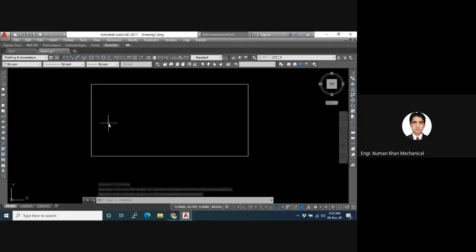There are three methods to draw a rectangle in CAD. The first one is if you know the starting point and the ending point, you can draw it just like we did in the limit X selection, where we were defining the lower left corner and the upper right corner. The next method is if you know the area of the rectangle and one side length, then you can draw a rectangle.